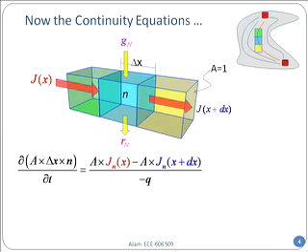So G sub n and R sub n represent electron generation and electron recombination, through trap-assisted recombination or direct recombination, that type of thing. And all you have to do is again multiply with the volume and G sub n, because G sub n is the number per centimeter cube per second. So that's the generation rate, and correspondingly the recombination rate.